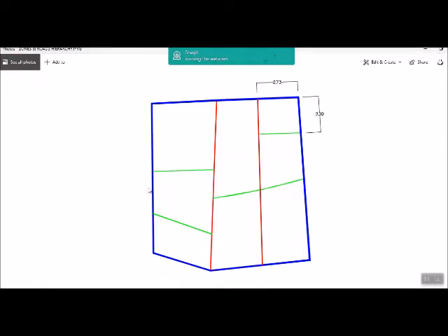The second thing that you are going to calculate is the trip assignment. You are going to assign the trips to this network in order to know the V over C, or the volume over capacity, of each road. And if the V over C is a huge number, this will give us a bad level of service.